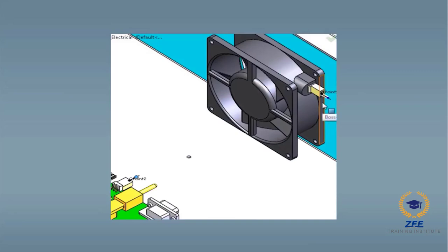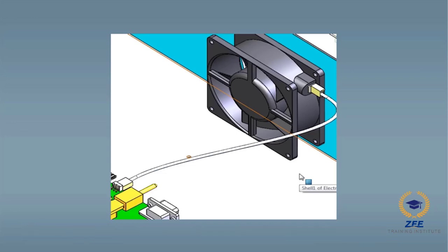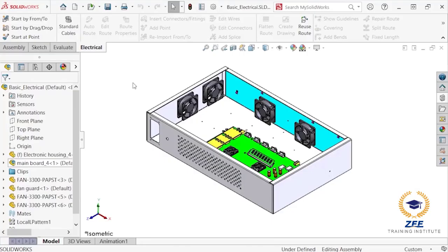Components that are used to begin or end a route also typically contain short sublines that represent a straight segment of wire, pipe, or tube that connect each component to the route. When dealing with electrical routes, the auto route functionality connects to the sublines using a spline, which can be manipulated to control the route, or you can use other routing components such as clips for further control.